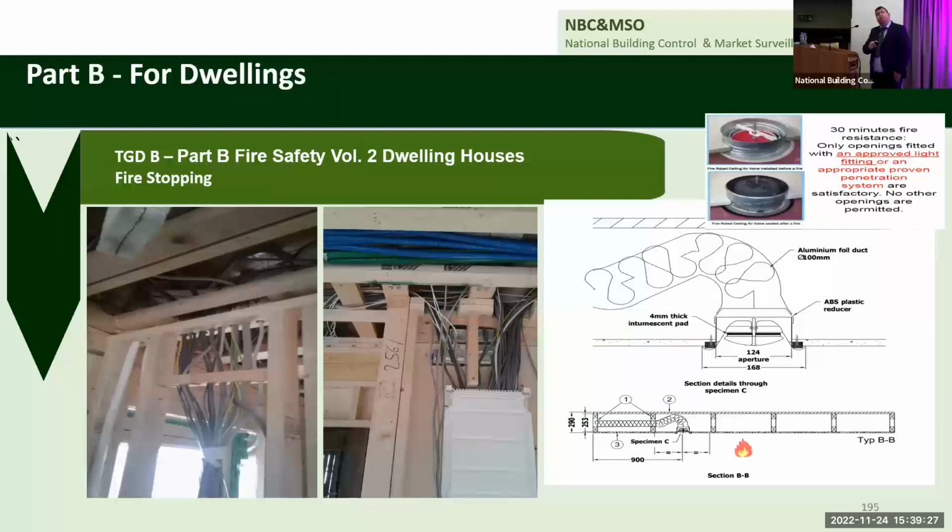We checked here, some of them have a wee red pad in it. When the fire happens, that will expand and fill that void. But who's checking to see, is it actually been the ventilator guy that's validating it? So designers and certifiers and inspectors need to check that that is being done.